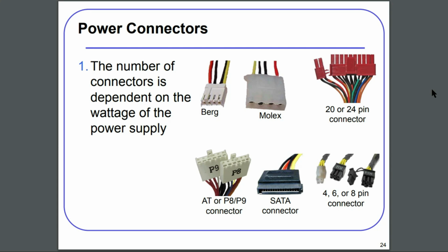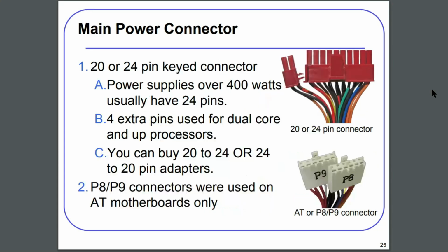In this slide we can check the different types of power connectors: Berg, Molex, 20 or 24 pin connectors, AT or P8 P9 connector, SATA connector, 4, 6 or 8 pin connectors. The number of connectors is dependent on the wattage of the power supply.